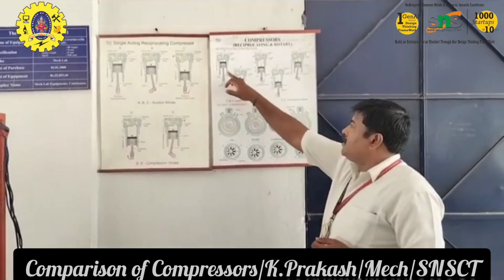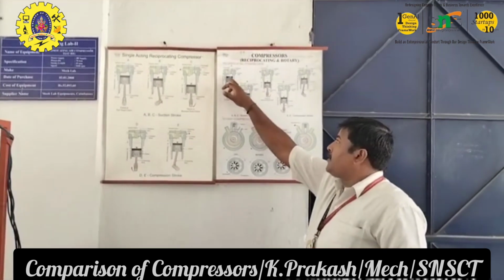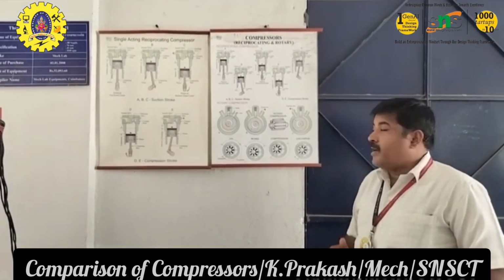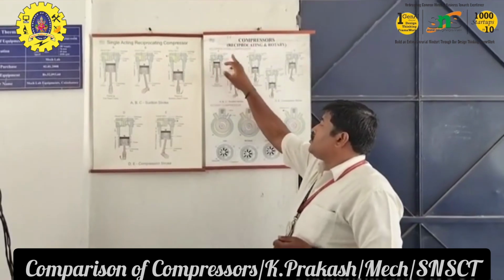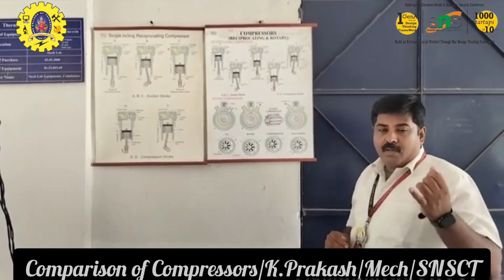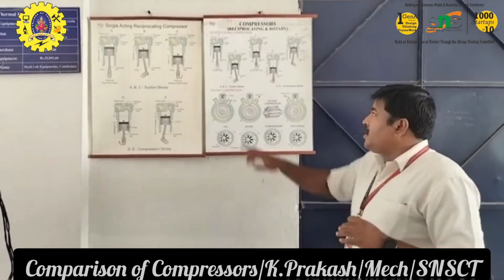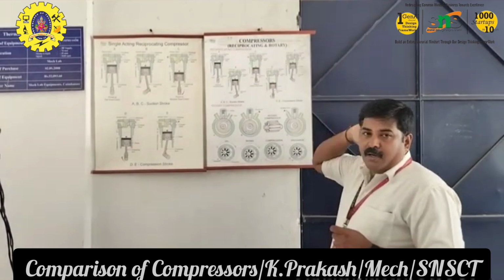When the piston moves downwards, air is taken inside, and when it is compressed to the required pressure level, the air comes outside with the required pressure. So suction, compression and then delivery: the three stages take place simultaneously in the reciprocating compressors.